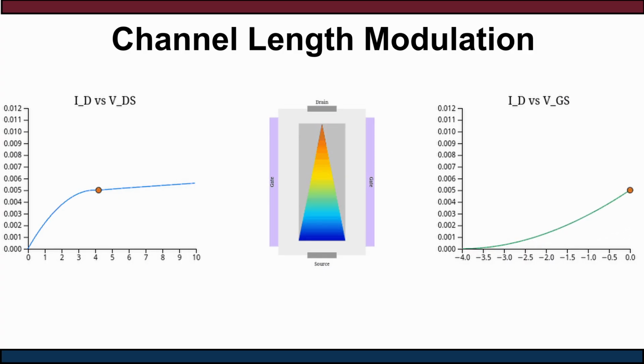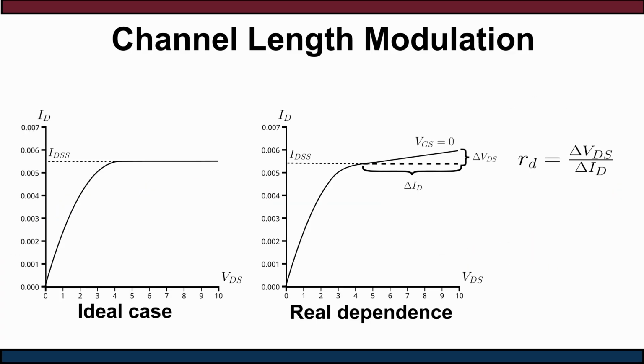If we slightly change VDS from 0 to 1 volt, we can stay in the region where drain current changes significantly with VDS. When VDS reaches 4 volts, the channel has minimal width and the point moves to the saturation region. In our ideal case, further increase of VDS should not affect the current, but in reality there is still a little influence. This effect is expressed in the slope of the curve. If we divide delta I by delta V, which represents the slope of a line in this region, we obtain the differential resistance of the channel in this regime.